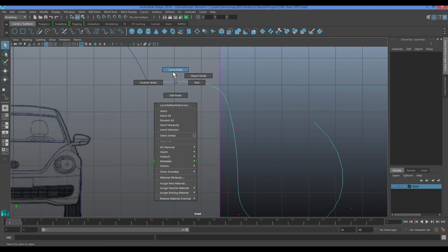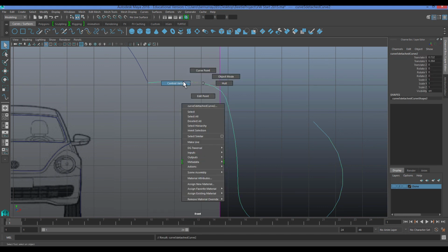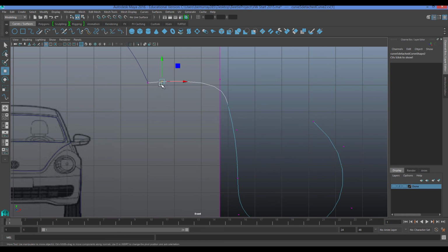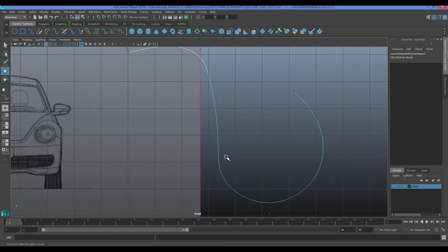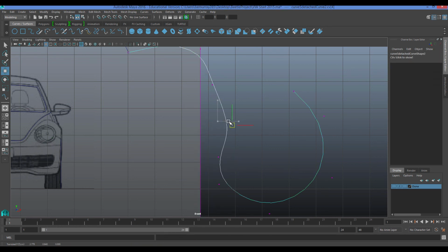So if I go to control point, curve point, click here, say insert knot, click that button there, then what we'll find is that there's an extra control point that it's going to add to it. So for example, if I want another point here, click, insert a knot, and you'll see it changes the curve slightly, and then go back to control vertex, there's now a point right there that I can manipulate.